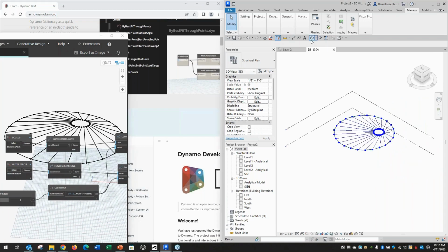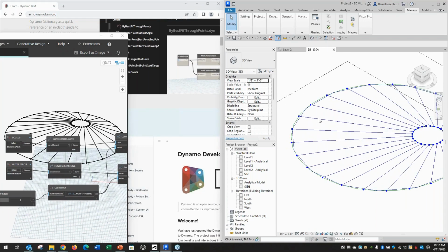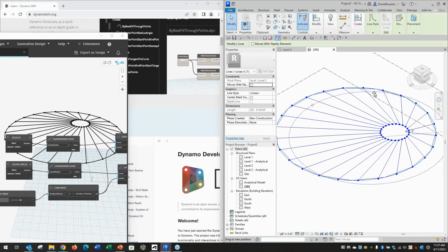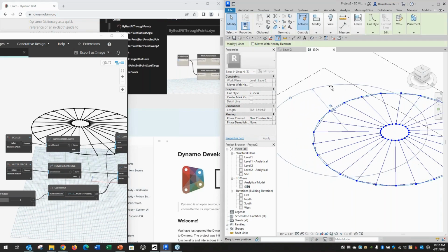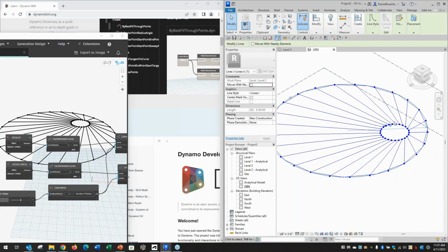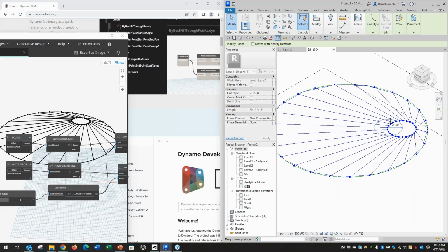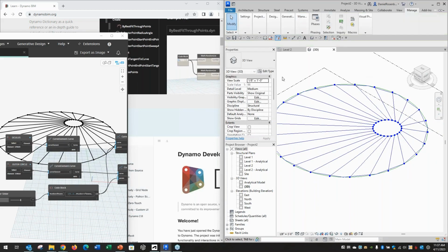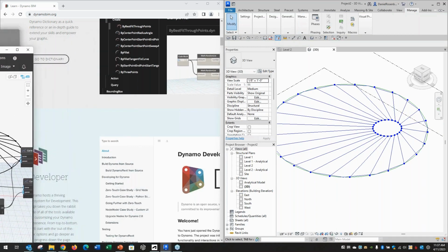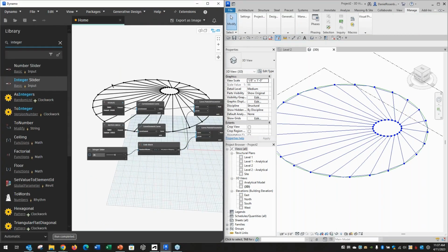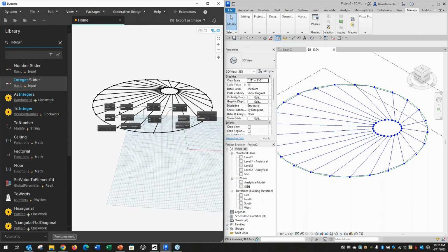Yeah, let's go to a default 3D view here. So you can see the model lines and the rig that we've built up. And if I move this around, it automatically updates. If I move the oculus or the outer, it updates basically exactly what I wanted it to do. So Dynamo's already helping me visualize this thing. It's already doing its job because it's all connected.